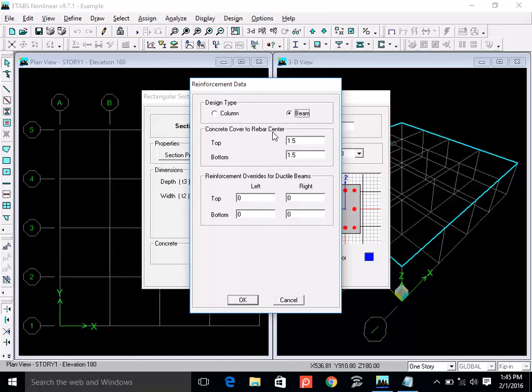They are easily available in the market. If you want a number 5 bar, you have to specially place an order and then we manufacture number 5 bars. You don't generally find them. In Pakistan, generally we have even-numbered bar sizes available. So we rely on number 4, 6, and 8 for longitudinal reinforcement, and number 3 for the rings. But in the case of bridges, with huge sizes, we may have number 4 as shear reinforcement as well.